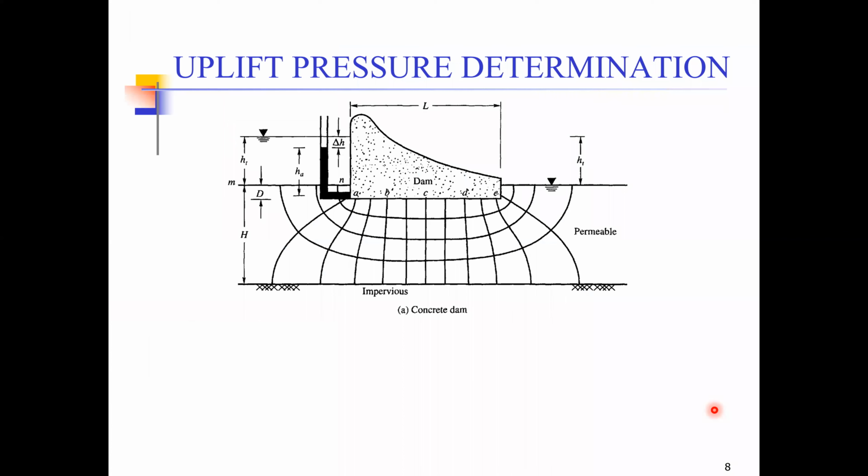Now, another important aspect that you should be aware of whenever we are talking about seepage studies beneath a dam structure: there is one important phenomenon that occurs when the water flows beneath the dam body. Let's assume that this is a concrete dam, and if it is a concrete dam, there is minimal flow of water, or no flow of water through the dam body, and all the water is flowing only beneath the dam body. Now when the water flows beneath the dam body, this flowing water exerts an uplift force on the dam structure.